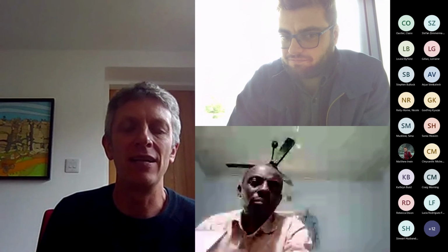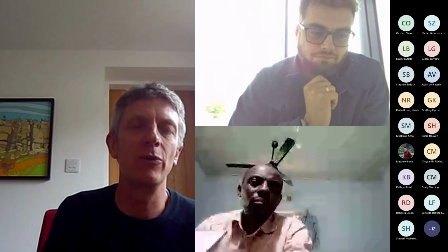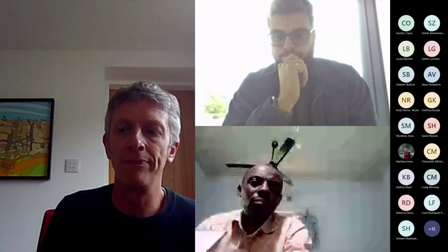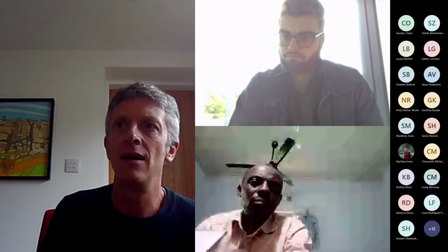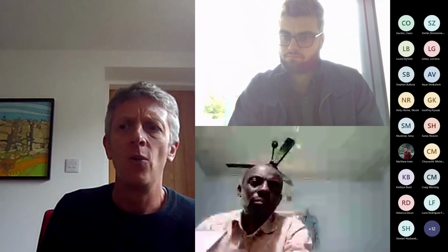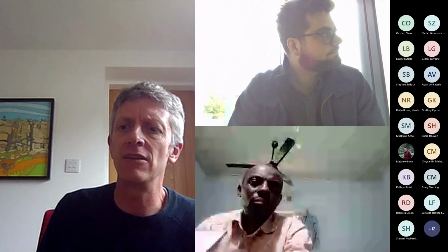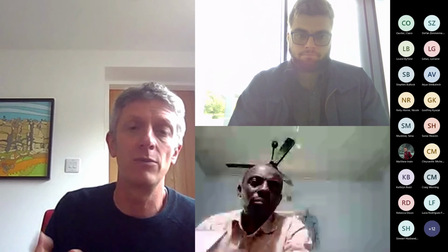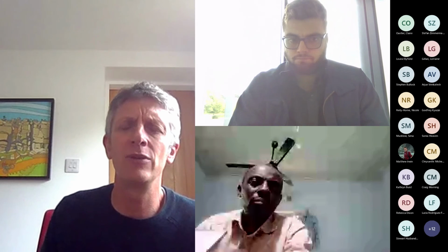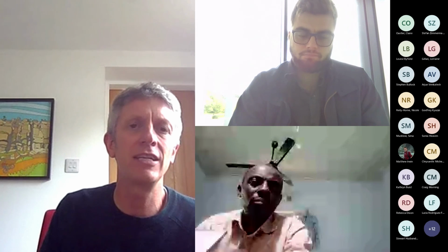Yeah, usually most of my research interest sparks up at the outlet from the treatment works, but there's a huge coupling from the treatment works through to what goes on inside the pipes, and even upstream from the source and how the source is managed, whether that's an upland catchment or groundwater. Then what the treatment train does, what standards you try to achieve through there. I think it was Amit Pinto who was looking at communities on filters and then communities in the bulk water in distribution networks, and was delighted with the finding. I think the number was something like 40% similarity of filter community and bulk water community.